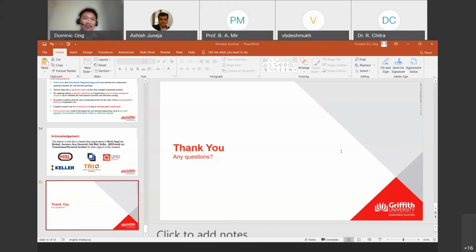Of course, if there's conservatism to be applied, I would suggest that you probably use something lower, and then discuss quality control with your contractor, because for every single stone column pile that's produced, you can see how much energy has been introduced to the individual pile. So that involves quality control on site. If, let's say, you want to design something to be worthy of those values, apply it exactly on site.